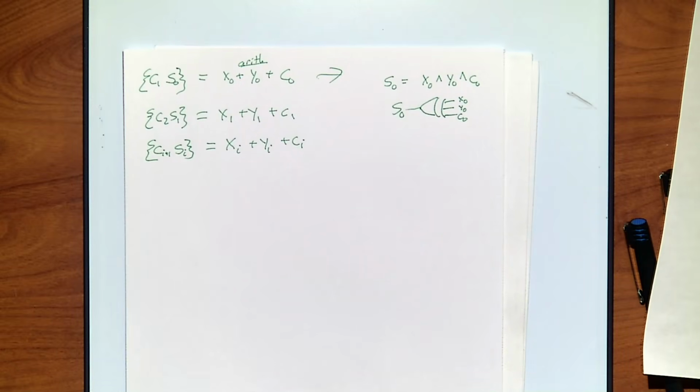But notice I have increased the width of the inputs to reduce the number of stages. It's a trade between how deep the stages are, which we consider proportional to the time it takes to solve, and the width of the inputs. It's a time complexity versus space trade. Give me wide inputs so I can consider multiple things together, and I can do it in fewer stages.